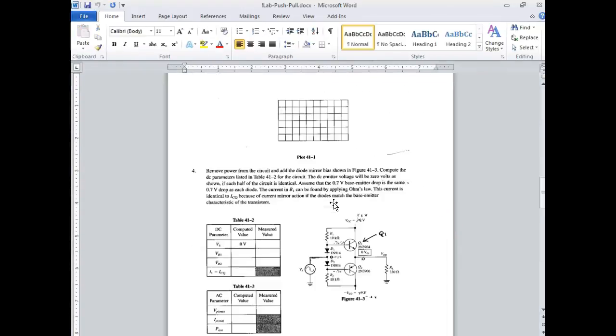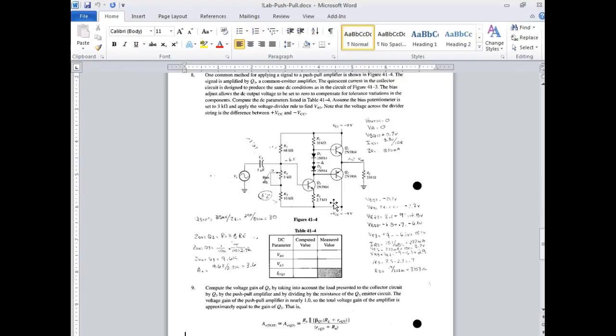So we called it, this guy has several names, a push-pull amplifier, because we have 2 transistors that are basically pushing and pulling against each other, right? So when this one cuts on, this one starts cutting off, and when this one starts cutting on, this one right here starts cutting off. And this is the math.